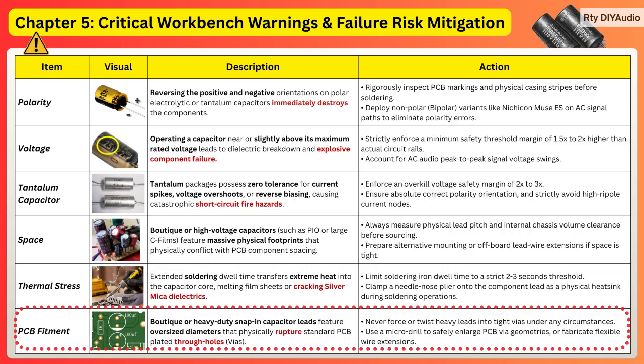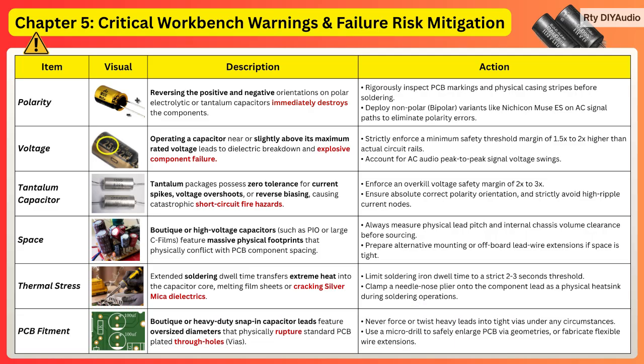a needle nose plier onto the component lead as a physical heat sink during your soldering operations. Finally, PCB fitment. Boutique or heavy-duty snap-in leads feature oversized diameters that physically rupture standard PCB-plated through holes or vias. Never force or twist heavy leads into tight vias under any circumstances. Utilize a micro drill to safely enlarge PCB via geometries or fabricate flexible wire extensions. Memorize these 6 Workbench laws to secure absolute reliability before executing your component swaps.